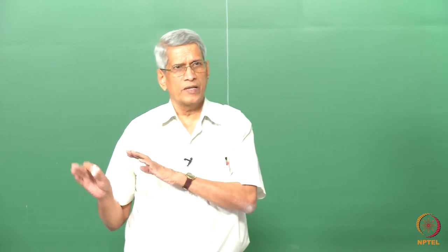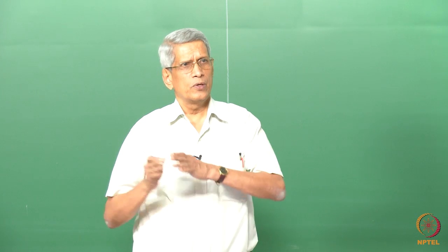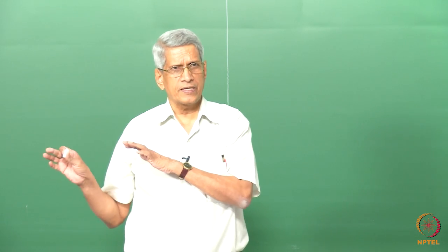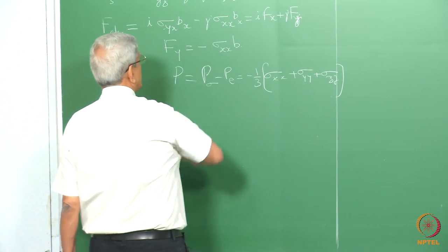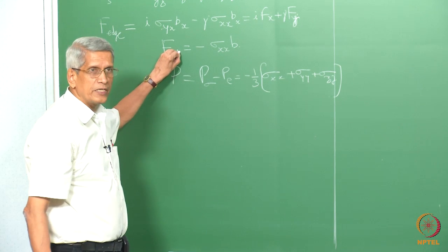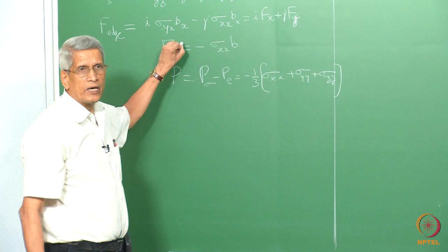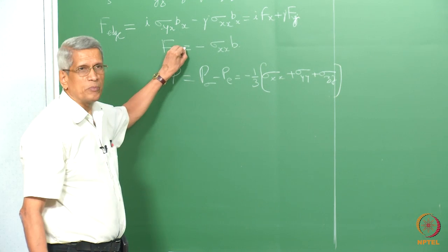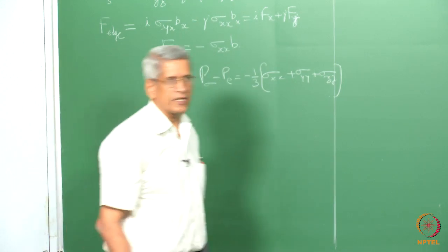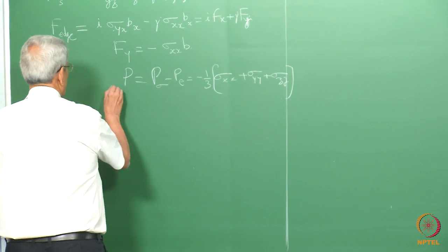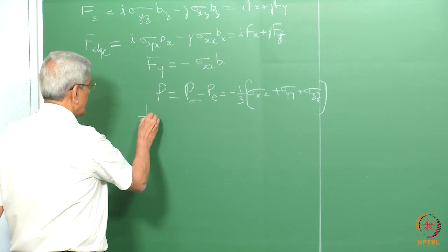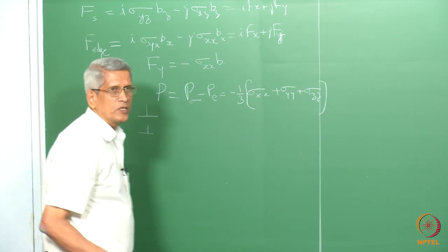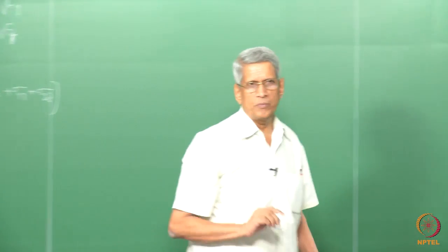As far as what we consider, when we know the external stress, this is Fy, okay, essentially nothing but the force per unit length of the dislocation. This will be essentially equivalent to the work which is being done to move a unit length of dislocation, right? Under the action of this, the dislocation is moving in which direction? The dislocation which is present is moving from here to here, correct? So let us consider one atomic displacement of the movement of the dislocation if it is taking place.